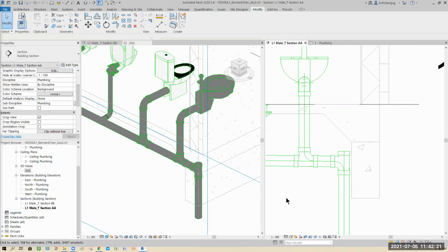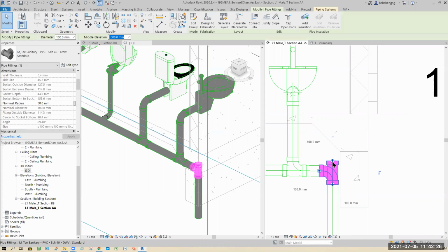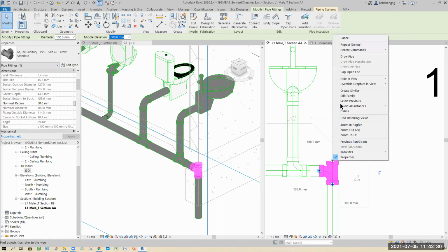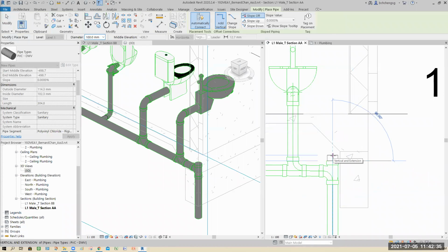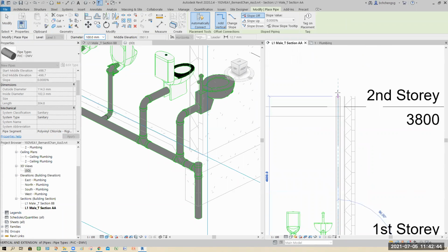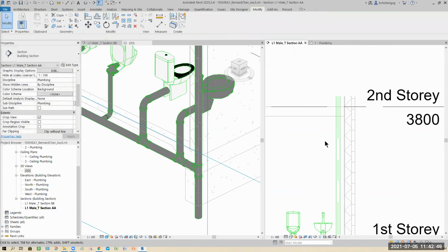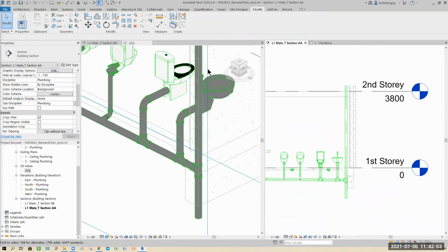Okay. So from there, you select the fitting, and you see there's a connecting point. Right click, you say draw pipe. When you select from PVC and draw pipe, it automatically becomes PVC. Then you just draw above, it can be seen like this, because of your section view. Okay, so temporarily we keep up to here.